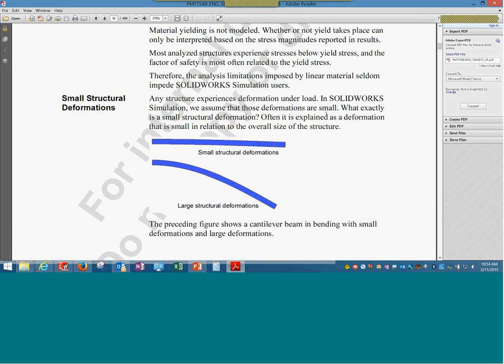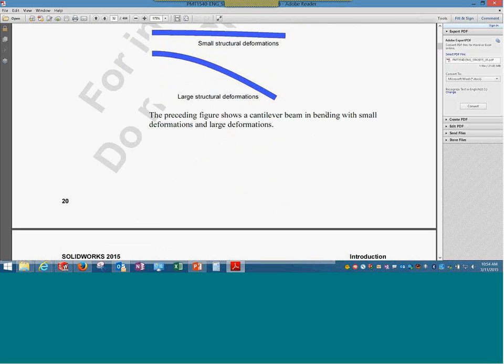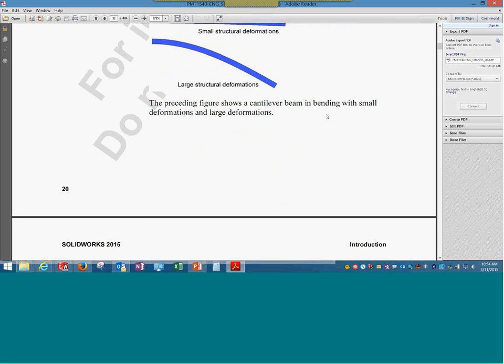So let me tell you that if it is an assembly with multiple parts, there is no point in using the parts. If there are any conditions in a static analysis wherein there is a gap between two parts and they are expected to contact after the forces are applied, the analysis is not eligible to be handled in static analysis or simulation standard.